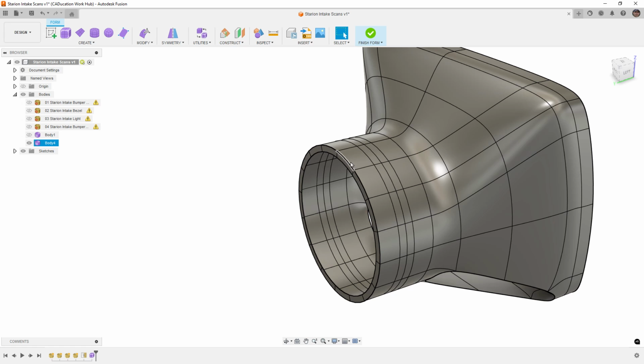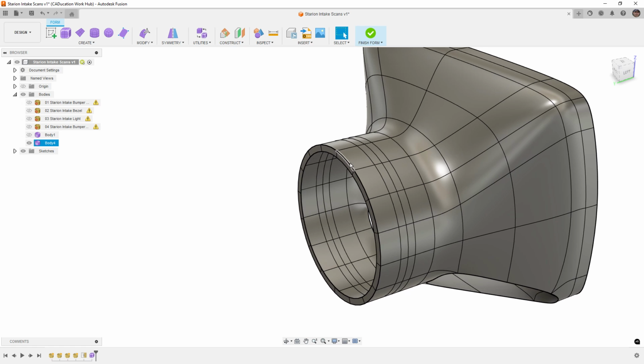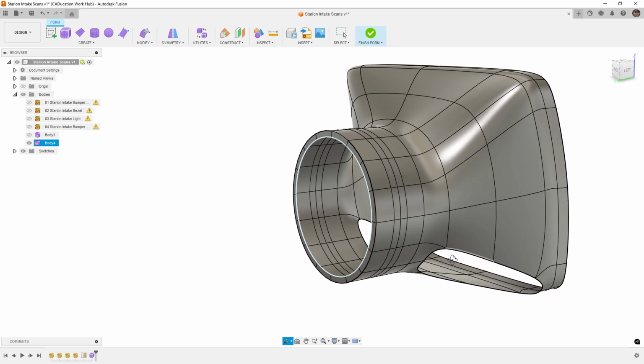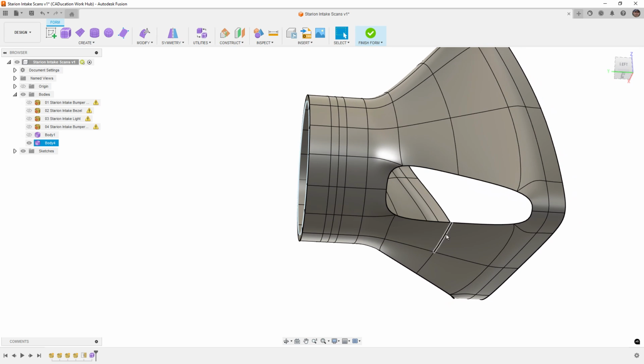And what this is doing is it's creating a crease on the edge. And with that crease on the edge, it kind of keeps everything in line as well. And you can go back in and you can freeze the center edge, and that'll theoretically hold that edge as needed. But sometimes it can be tricky. You'll find that it will remove the frozen edge and you'll have to go back and kind of fix it.